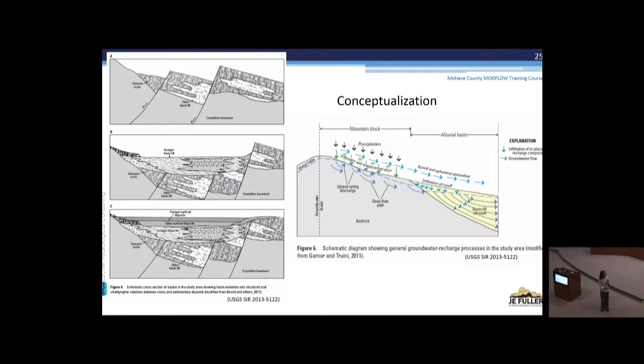The basin opens up, mountains here get eroded a bit, and alluvial deposits form in the middle of the basin. And you can see right here, this little blob is an area of alluvium that was probably an ancient lake or maybe an ancient sea, and it is very low permeability relative to the stuff around it, which is more coarse-grained. So if I were going to drill a well, I would aim for outside this blob and not directly in it.